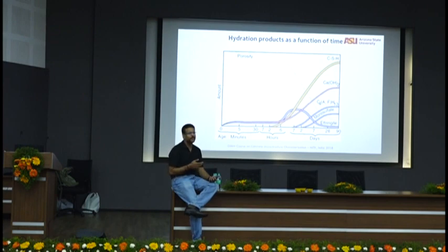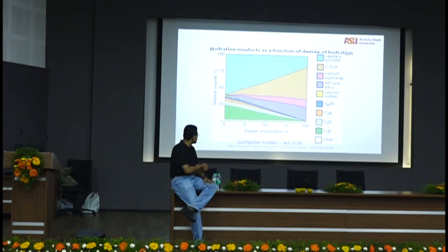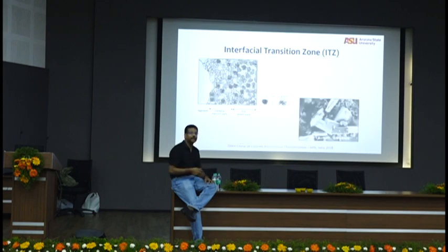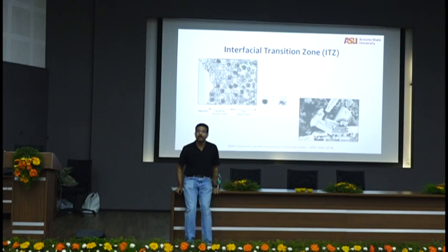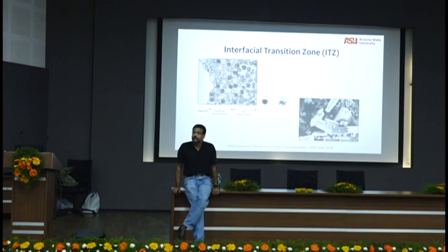About 10, 15, maybe 15, 20 years ago, ITZ was a big question of debate. It's very simple. If you think of nucleation, nucleation needs surfaces, sand particles are surfaces, crystalline materials precipitate first. Of course, there has to be porosity. Right? That's what is happening. And so you will have interfacial transition zones. There's a way to reduce interfacial transition zones. There's a way to make the ITZs more dense. It's by typically putting materials like silica fume.